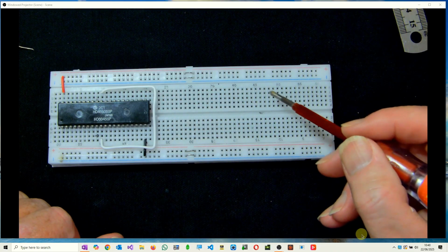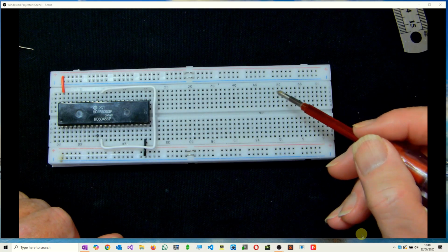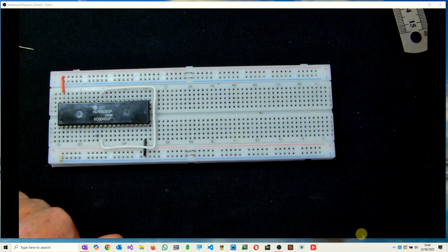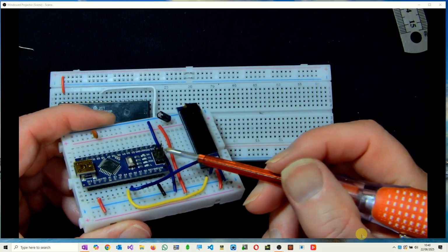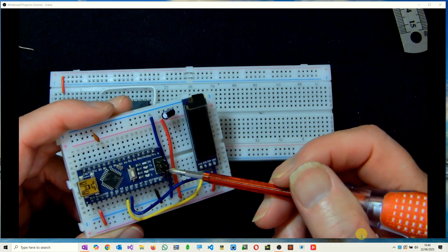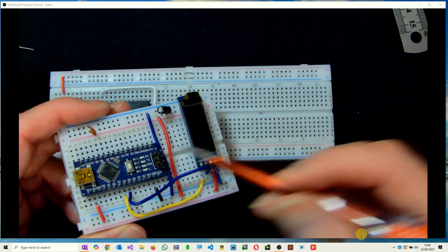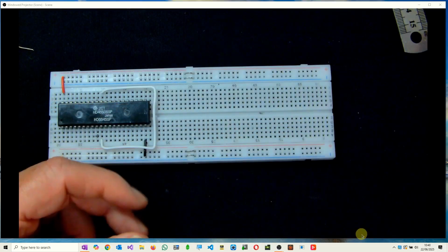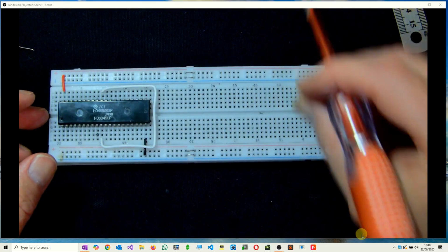If you're doing some analog work, then what you can do is build it on a perf board and then put some pins in it which will plug straight onto the board. That's an alternative. In fact, the same pins as you'll find on here, which is an Arduino, they're also 2.54 pitch, and then you can put these pins into the board, and you can plug a socket directly in and plug your board in, or you can solder them into the perf board and just push the board straight in.